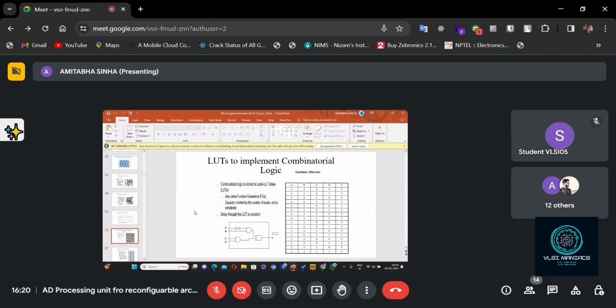Here, let's say in a complex functioning, when you are dividing into many logic blocks, many of them can work concurrently, in parallel. So it's basically hardware implementation. You are programming it, it's true, but this programming is basically hardware programming. So the concept of programming a von Neumann computer and the concept of programming an FPGA is totally different. It is reconfigurable in the sense that by programming you can change it.